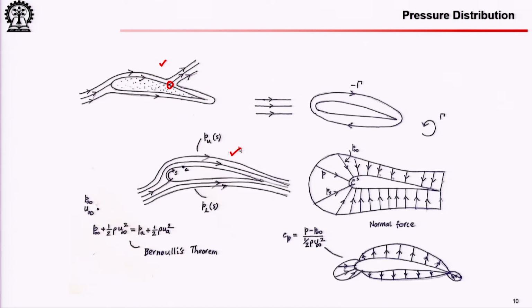So, something is happening that is moving this rearward stagnation point in such a way that flow leaves the trailing edge smoothly, and we said that is something which is popularly known as the Kutta condition. That is, you will never have the rearward stagnation point somewhere on the top surface or on the bottom surface, and part of the reason was flow does not like to bend across these very sharp turns, that leads to infinite velocities and very large gradients of other flow field parameters.